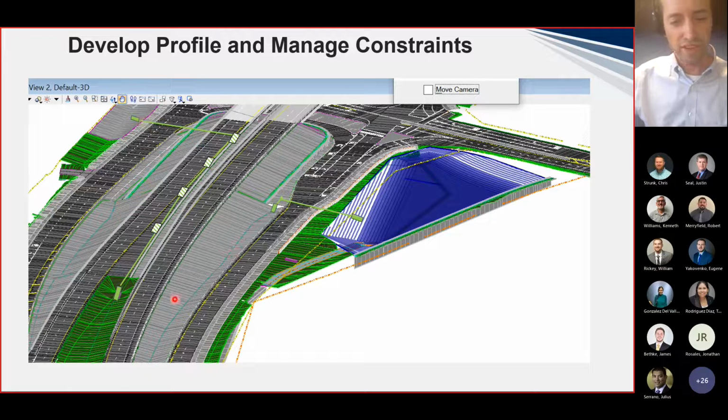And then we have a concrete riprap line ditch on this side that's draining as far as we can, and then being captured in a SET, connecting to a manhole, dropping, going under the frontage road into the pond.